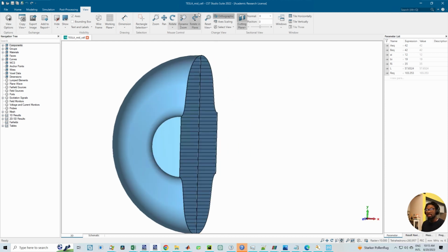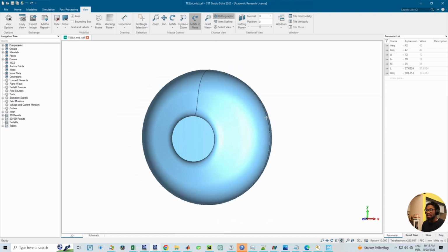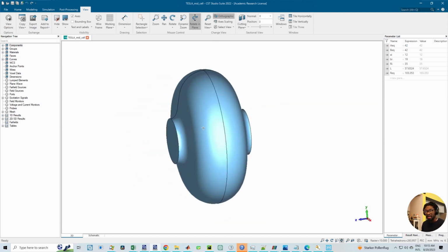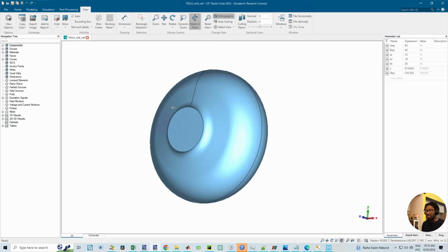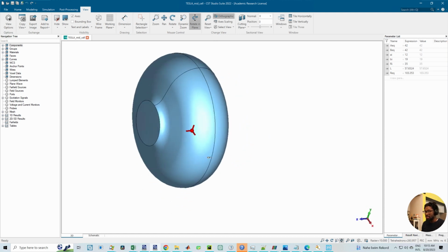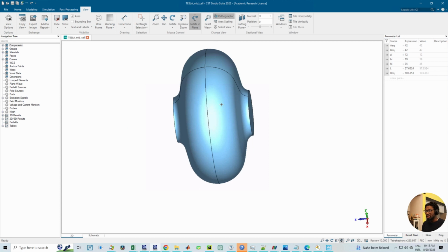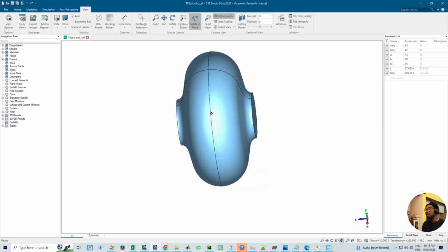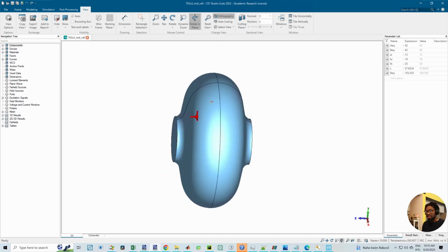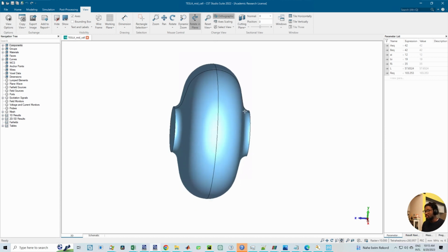Now, since the simulation would need a high mesh refinement, I am just going to analyze the mid cell of the cavity instead of conducting eigenmode analysis for the entire cavity, as it would save more time. The second thing to note, or the first and most important thing, is that for multipacting analysis using the PIC solver, you would need a hexahedral mesh, because you would first calculate the fields. You could do this in time domain, or you could use the eigenmode solver.